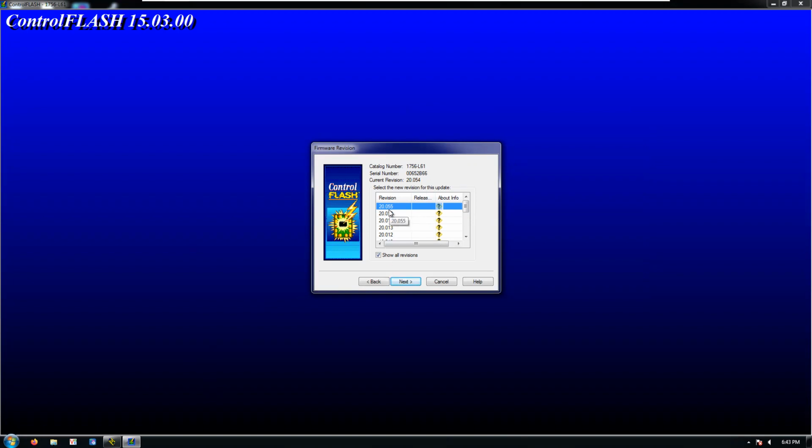So that means if you find an operating system, or you find a control system with one of these processors, and let's say you wanted to read from it from a brand new piece of software, well, that brand new piece of software might not be able to communicate with an old firmware. So you might need to upgrade the firmware to a newer version of it. Well, now if you've got an L61 in the field and you can't come to version 28, now you got to get a new controller. It is a huge pain in the butt.